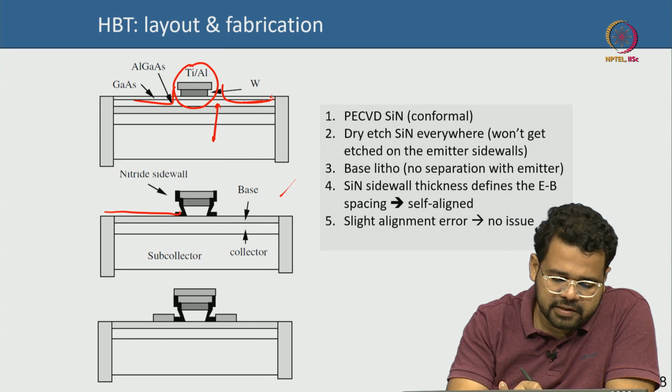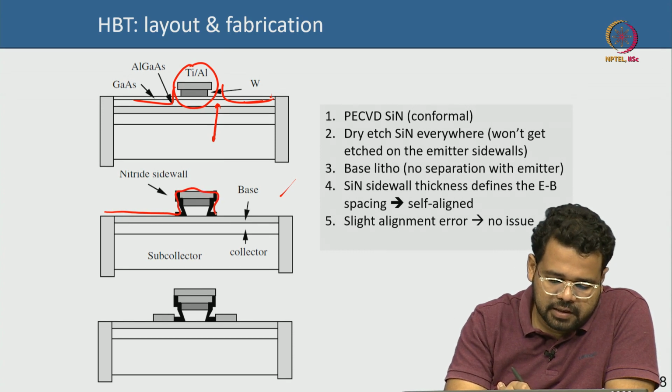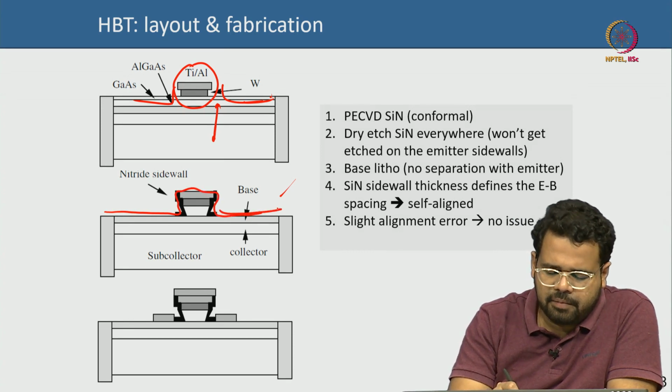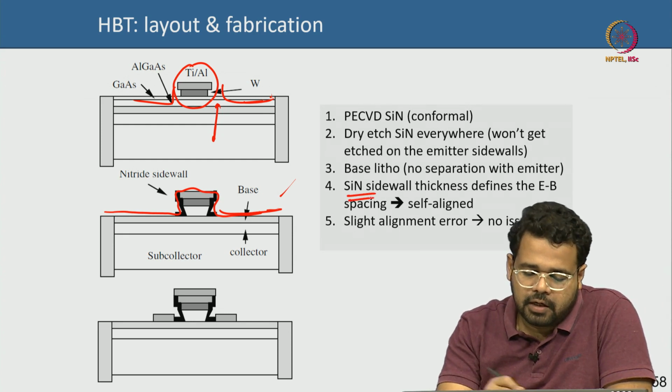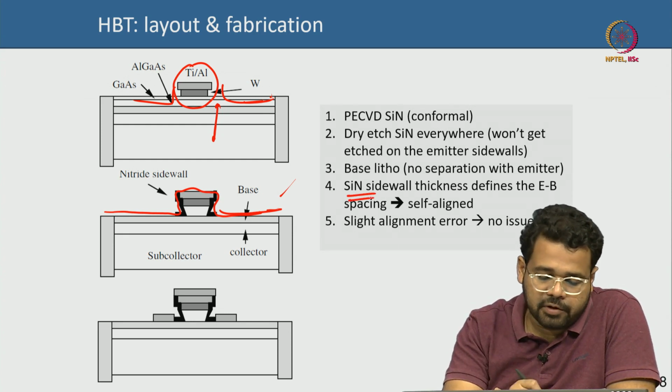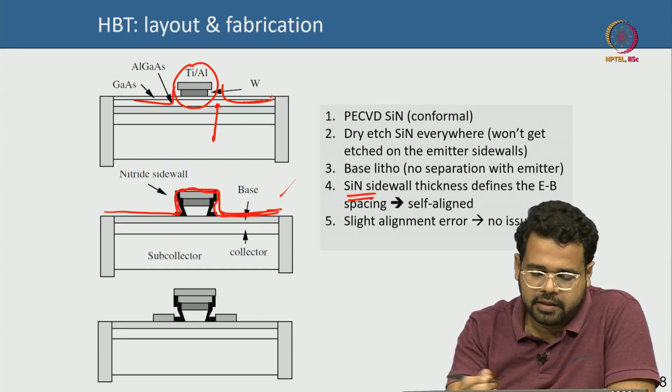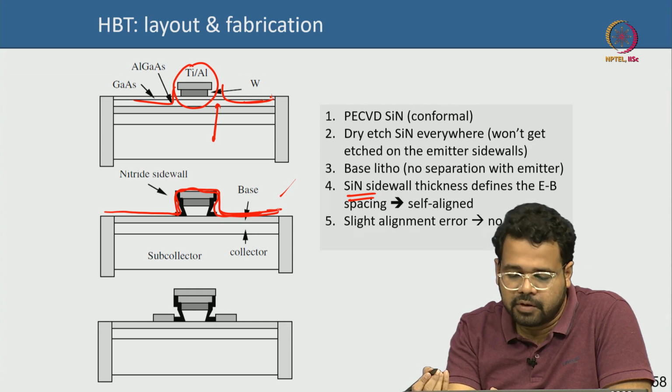So you have silicon nitride just like that, okay, silicon nitride just like that. This is a thick layer, maybe a couple of 100 nanometer of silicon nitride you use. Now it is depositing conformally, which means it is depositing everywhere, on the bottom, on the side, on the top, right, and it has a certain thickness, few 100 nanometer for instance.